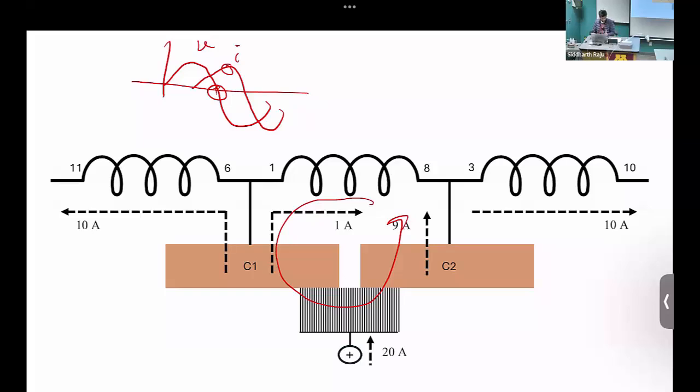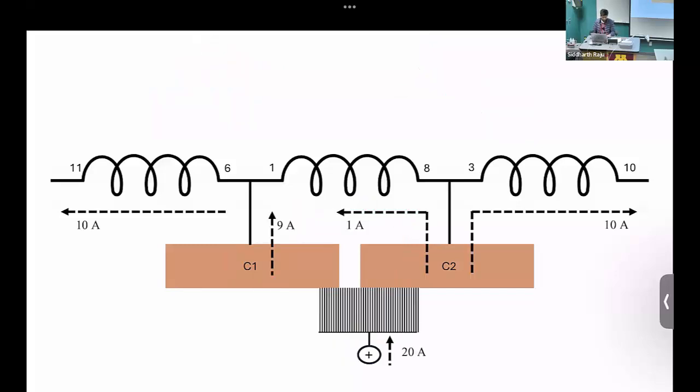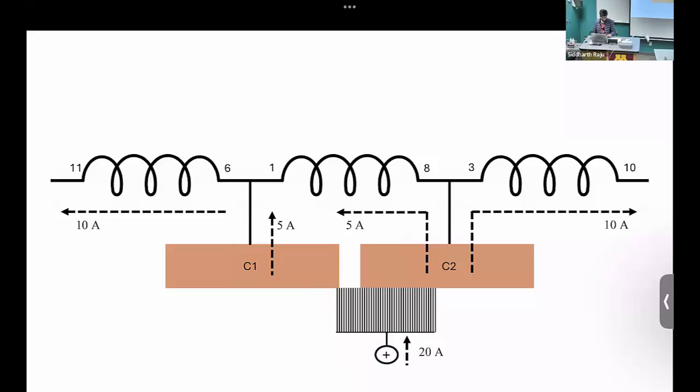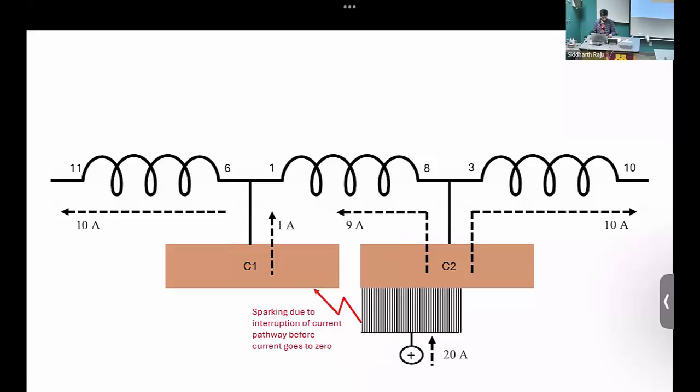So let's assume that it doesn't fully go to zero. There is some amount of current because of the inductive nature. The voltage has gone to zero. This was the case of pure L. If it was an RL network, there would be some phase shift between the current and the voltage. So when the voltage goes to zero, the current is still some tiny, but non-negligible, non-zero value. So you can extend this process forward. Once the full thing is completed, the current needn't have fully gone to zero.